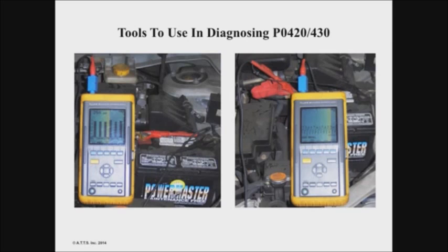But even using an old tool like this, the Fluke 98, okay, we could see a bar graph, and you know how long that takes me? Less than 2 minutes. I disable fuel, I'm at the battery positive negative. I tell the guy in the car, dude, crank it over. I crank it over, and 1, 2, 3, I could see if I have a problem. Let's say you don't have this scope. Pete and I have done the Pico scope on one of the things, and Bernie scope as well.